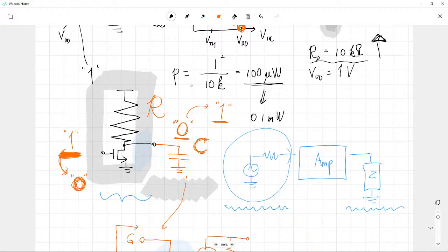Then think about how we can increase the voltage assigned to this node. Simply speaking, when we have this NMOS inverter attached to the load capacitor, the output voltage is given by this capacitor voltage, and in order to increase this capacitor voltage, we have to provide a sufficient amount of charge into this node. Then who can provide the charge into it?